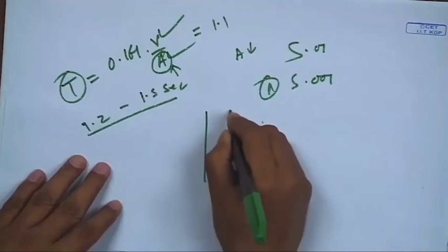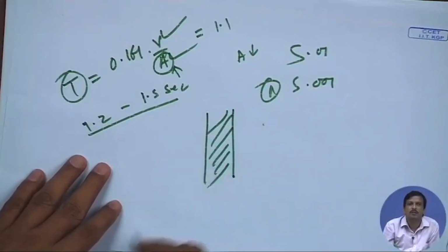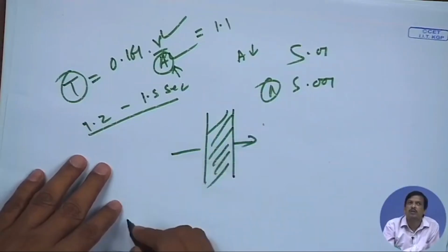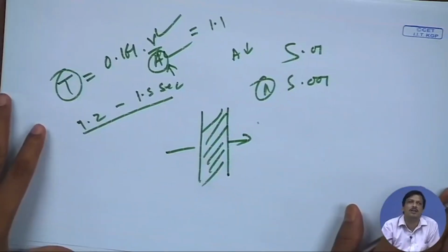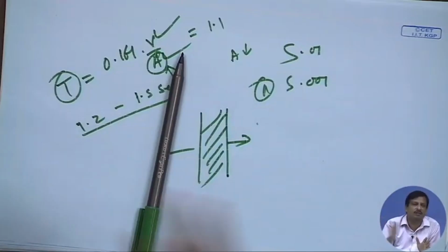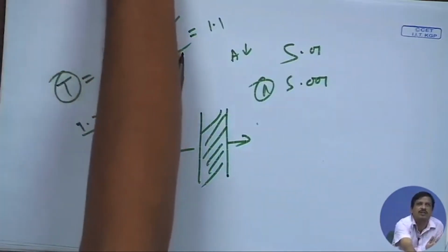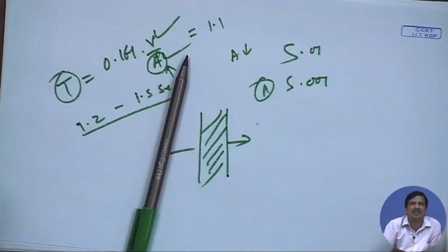So, what I will do, I make an air gap inside the door, or I put an acoustic blanket in the middle of the door. I make two wooden plates and then put an acoustic blanket here. Then the sound transmission will be reduced. So, that kind of consultancy you have to provide to the engineer. So, this is the auditorium design. Let us try a design of this kind of auditorium, the real part. Then if you have any query, then you ask me, then if I know, I will answer it.